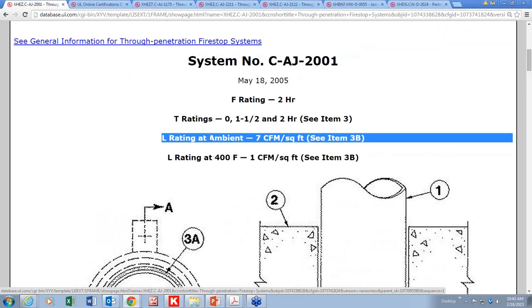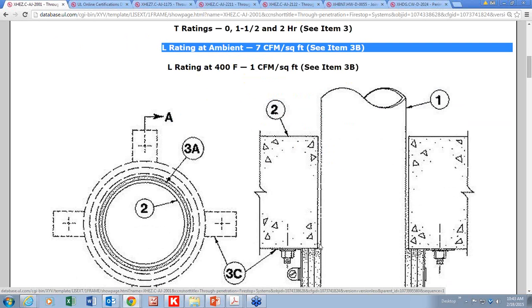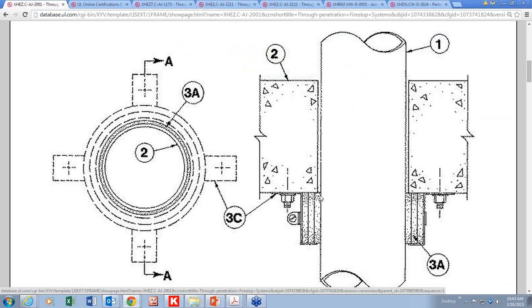If the building official looking at an existing building goes through and says you've got violations, go get some firestop, what will happen is they'll come back with a tube of firestop sealant and put a bead of firestop sealant around the perimeter of this plastic pipe. That winds up being a fire risk. Why? Because we didn't ask for the right thing. We need to ask for a firestop system, which will use firestop products to restore the fire rating that the wall had before somebody poked a hole through it or put a joint in it.